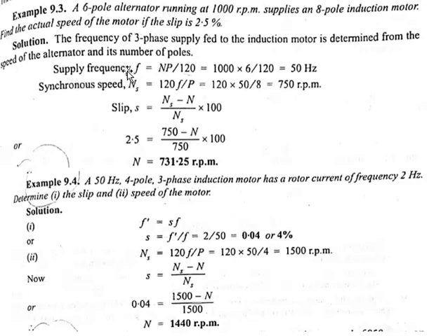What is the frequency of the alternator supply? f is equal to N into P divided by 120. If you remember, we did this derivation. Here N is the speed of the alternator, 1000, and P is the number of poles of our alternator, divided by 120, we get 50 hertz. So 50 hertz is the supply. Using that value, you can calculate 120 into 50 divided by P, where P is the number of poles on the induction motor, 8. We get 750 rpm as the synchronous speed.